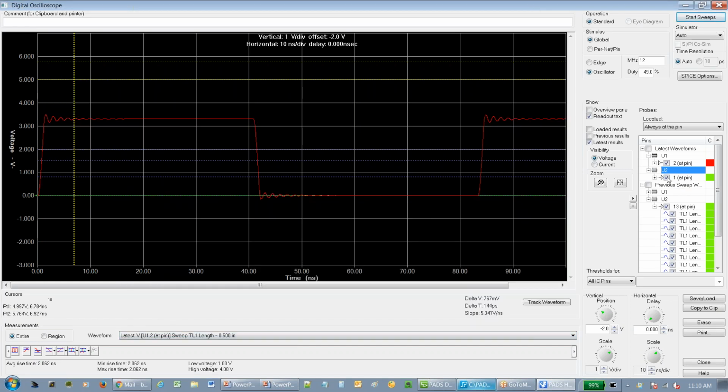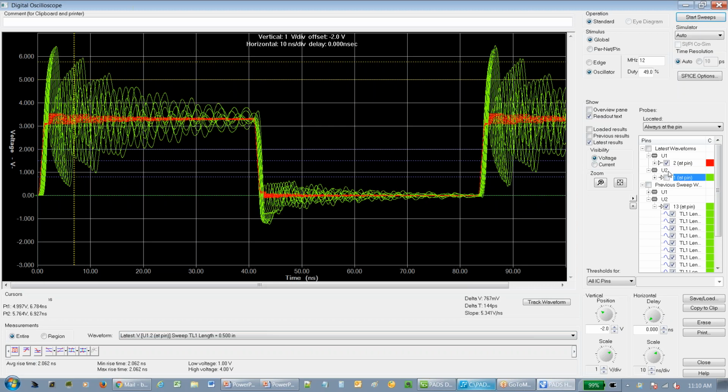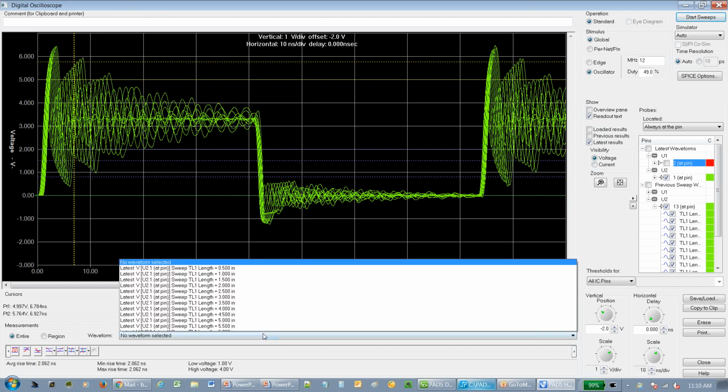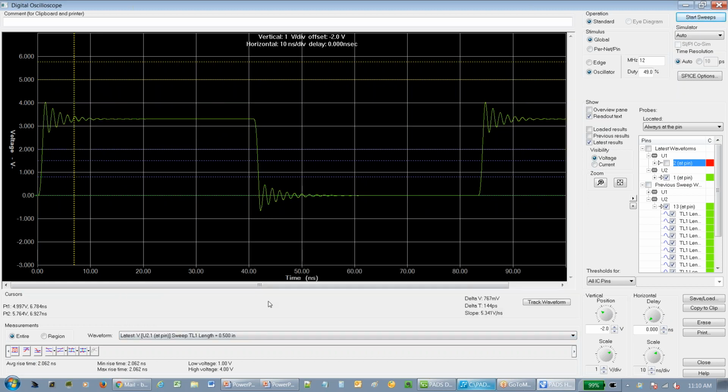Let's go back to the 1/2 inch signal here. Oops. Yeah, I want to look at the receiver. All right. So there's the receiver at just a 1/2 inch. And if I look at the edge rate real quick on here, this one happens to be pretty fast. This is a 400 picosecond edge rate. But now you can see as the edge rate starts getting faster and faster, the trace length is becoming a bigger and bigger issue. So everything is all about that edge rate.